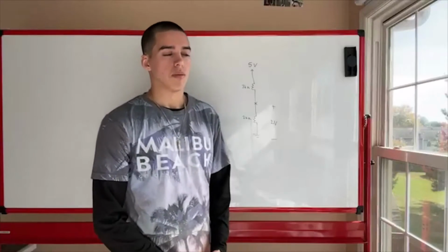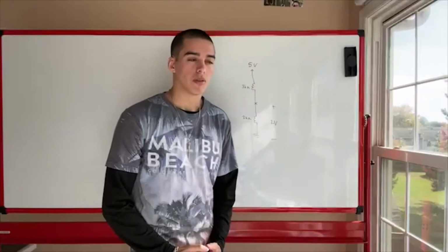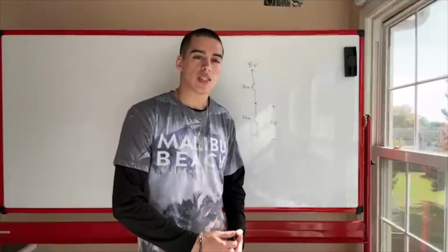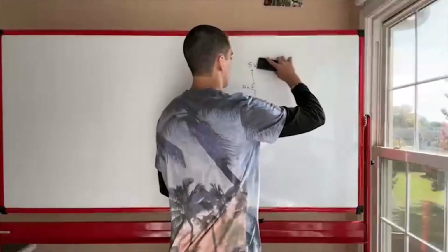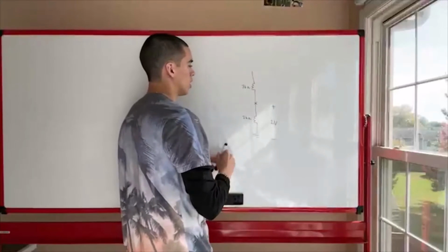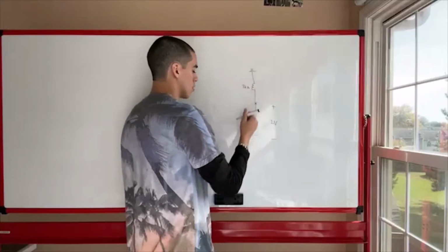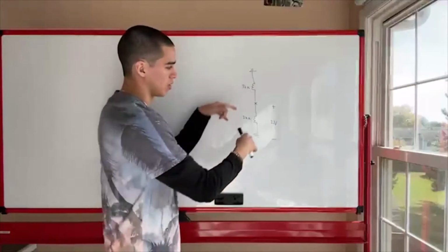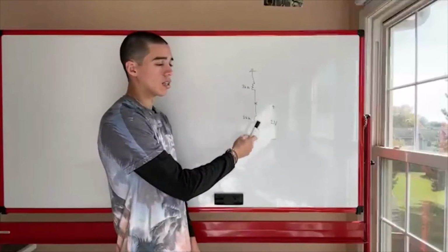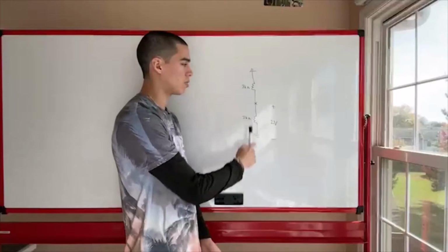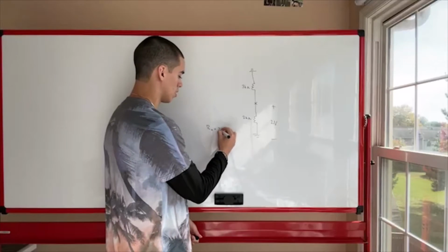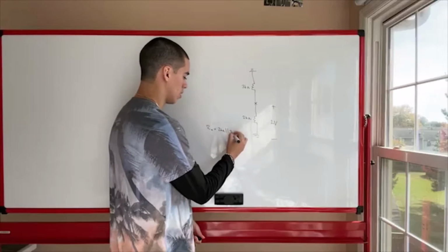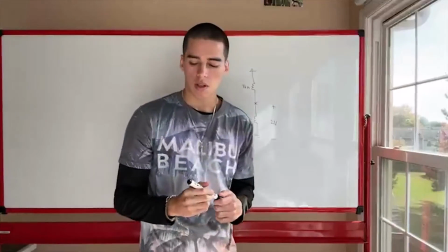So we want the equivalent output resistance measured across the output terminals. The equivalent resistance seen across two terminals is the Thevenin equivalent resistance. And to find that, we short the voltage source. Okay, and then we find the resistance across the terminals of interest. So if you can bend that in your head, then you'll see that the equivalent output resistance will be 2 parallel with 3, and that's RO, or the equivalent output resistance. If you don't know how to do Thevenin equivalent, I'll have a video about it soon, and I'll put it in the link.